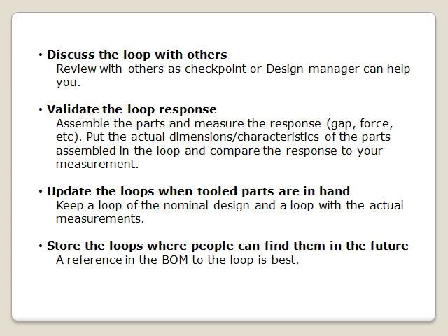Discuss the loop with others. This is a very important point, because our path and the calculation of the tolerance stack-up analysis will depend on it. Review with others as a checkpoint, or checkpoints, can help you. Validate the loop response: assemble the parts and measure the response. Put the actual dimensions and characteristics of the parts assembled in the loop, and compare the response to the measurement. Update the loops when tool parts are in hand. Store the loops where people can find them in future.